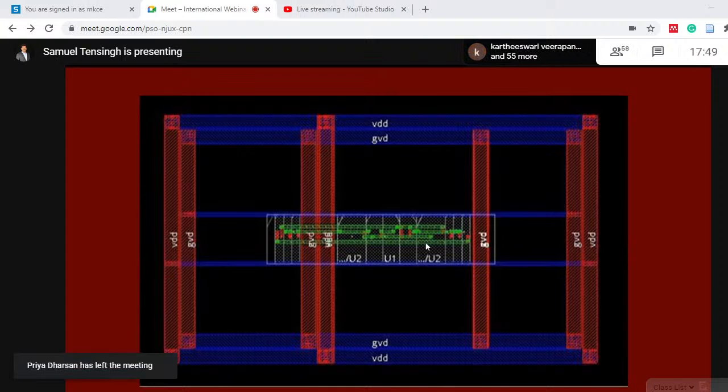So for each nanometer technology, the companies will have the standard cells ready. They will be stable for each technology, so that when you get a project, if it's a 40 nanometer project, all the standard cells of the 40 nanometer library will be installed in your database. When you source your environment and import your floor plan, all the 40 nanometer cells will be in your design. These have already run through all the physical verification checks, making sure that the internals of the standard cell are clean.